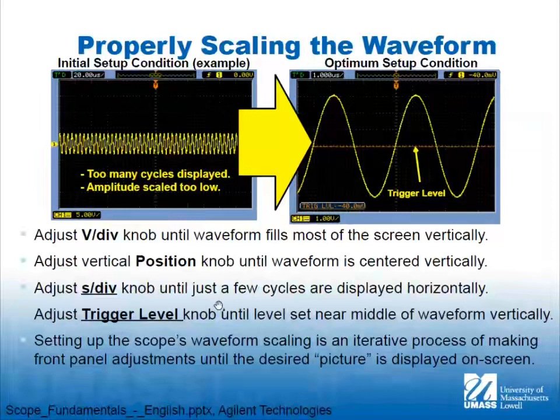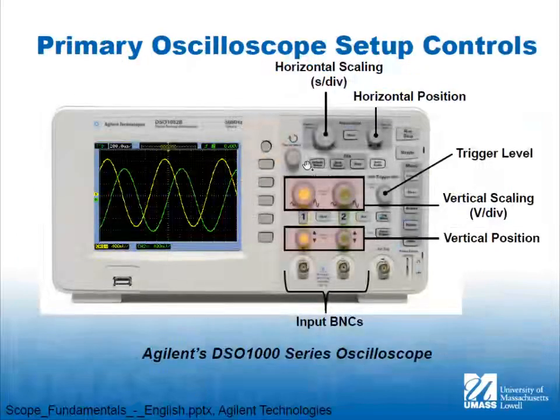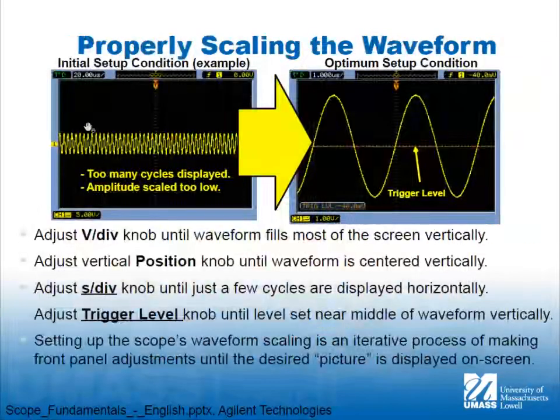And I'm just going to step back one. This scope doesn't have it, but a lot of scopes, oh yeah, it does right there, auto scale. So if you're measuring something like this and you press auto scale, it's going to end up giving you a signal like this. So depends, right? I usually hit auto scale. It gets a signal about what I want and then I make adjustments to get exactly what I want to see on the screen. Sometimes you want to see a lot of detail in here, and it's a sine wave. So you blow it way up and the signal, that rising edge sweeps across the whole screen, but you get a good view of what's going on, especially with digital signals that have bounce in them, right? So you can see that bounce in the slope.